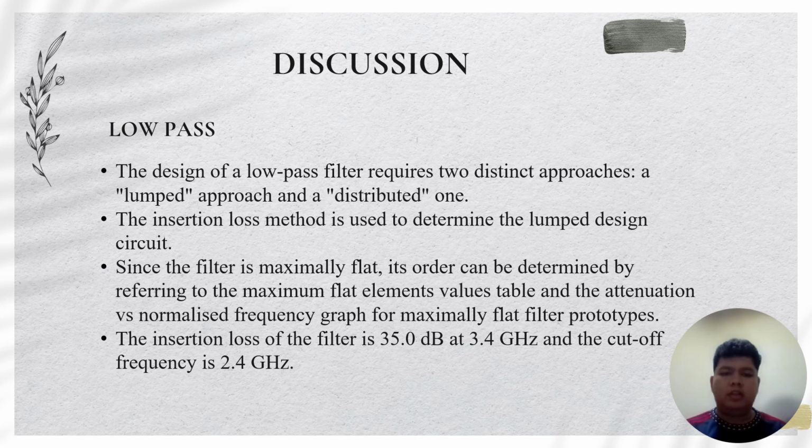Since the filter is maximally flat, its order can be determined by referring to the maximally flat element values table and the attenuation versus normalized frequency graph for maximally flat filter prototypes. As we know, the insertion loss of the filter is 35 dB at 3.4 gigahertz, and also the cutoff frequency is 2.4 gigahertz.